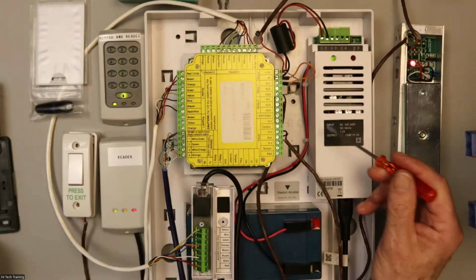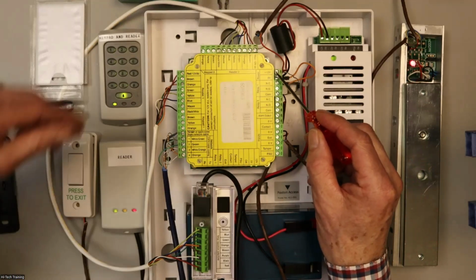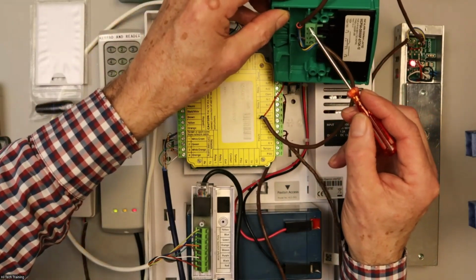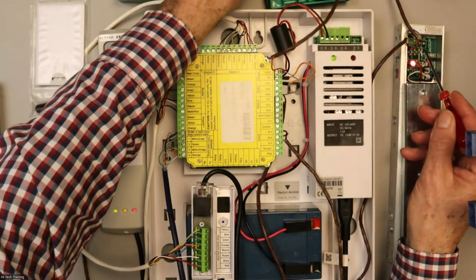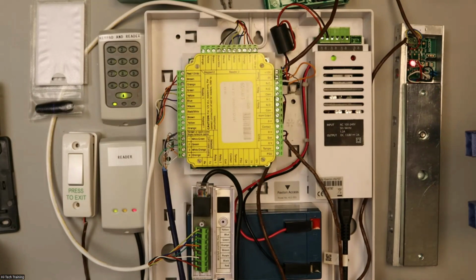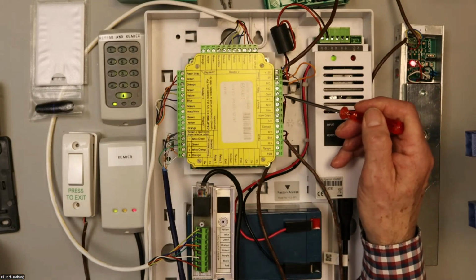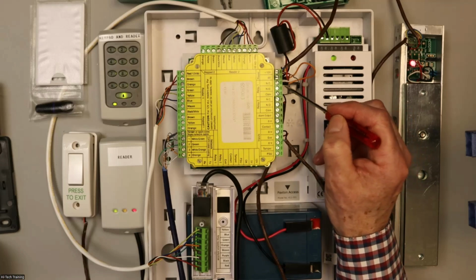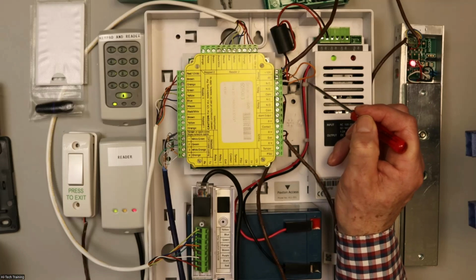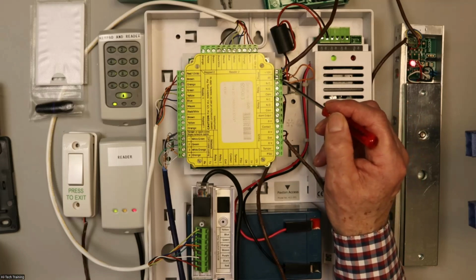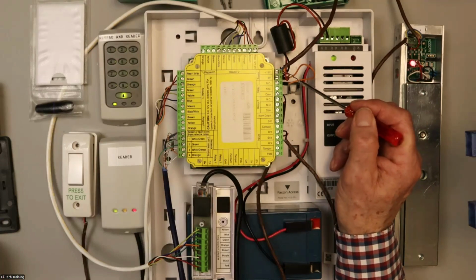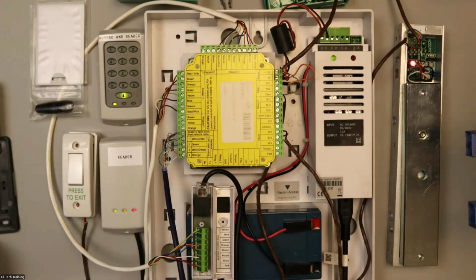Okay, lock connection. You've got the plus in the lock here, going out into your break glass unit, out of this, in here to plus on your lock. Out the minus comes down this cable here, around there. Minus comes to here, so you're normally closed. And I put a link in here between normally closed and 0 volts to return back to my 0 volts, to give the negative for my lock. There's my back EMF diode between the plus and the minus, with the cathode on the plus side. It's got to be done the right way around.